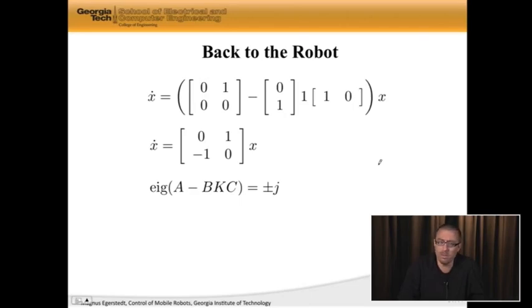So is this system asymptotically stable? Well, the real part of lambda for both lambdas, so we have 2 lambdas, the real part is 0 because this is a purely imaginary system. And as I said last time, if I have 2 imaginary eigenvalues and all the others are well behaved, in this case I don't have any others, then I have a critically stable system.